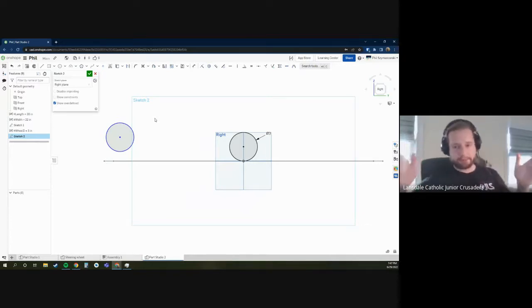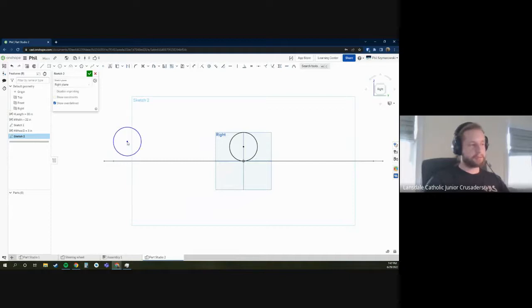They will cause a lot of friction when you try to rotate. Imagine trying to take your car and rotate it in place. It would be really difficult, right? And the wheels would squeal and everything. That's kind of what we try to avoid by raising the outer wheel by a little bit. And I'm going to show you how I would sketch that.